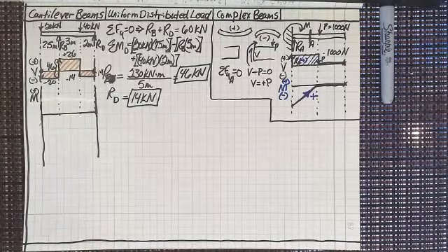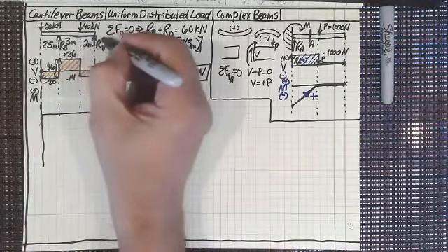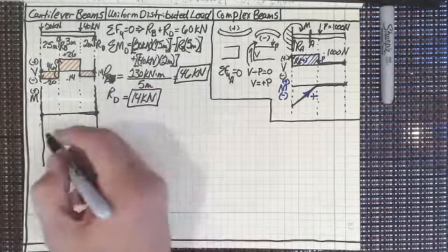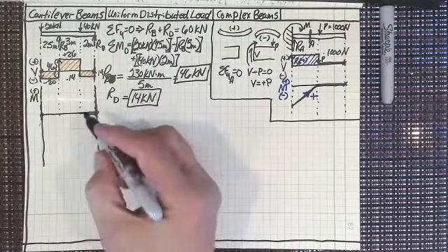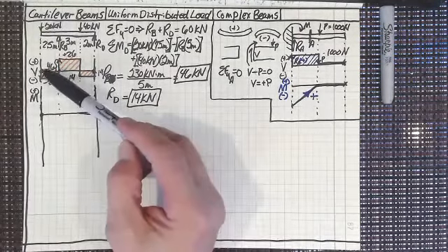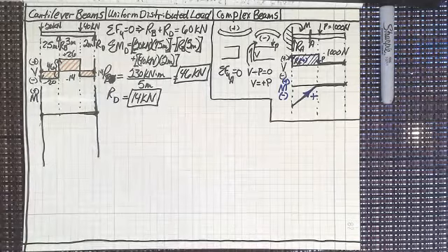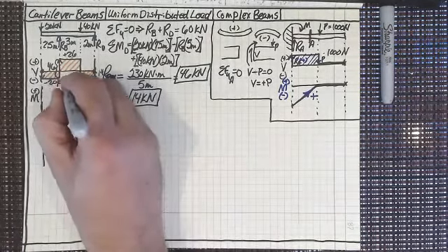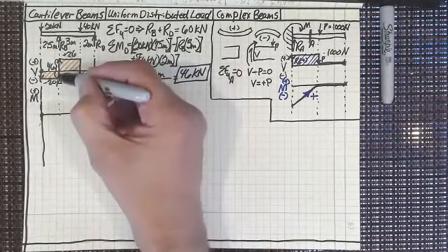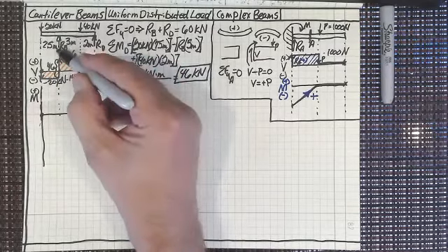All right. Now, what is the bending moment diagram? How are we going to figure this out? We know that on a complex beam, we begin and end at 0. So we know we begin and end on 0. The first thing we're going to do is go down minus 20 kilonewtons. But it's really the slope down here, because we're integrating this into this. The slope will be minus 20 kilonewton meters per meter, and we're going 2.5 meters.